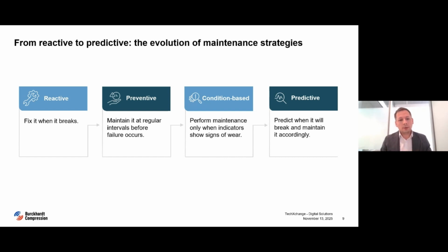That leads to the next, much more informed approach, which is called condition-based, when the performance of a certain component is tracked, usually in real time, and based on indicators, the decision is made to maintain a component, replace it, or refurbish it in a certain way. And these strategies, these approaches, are not optimal when they are applied on their own and alone.